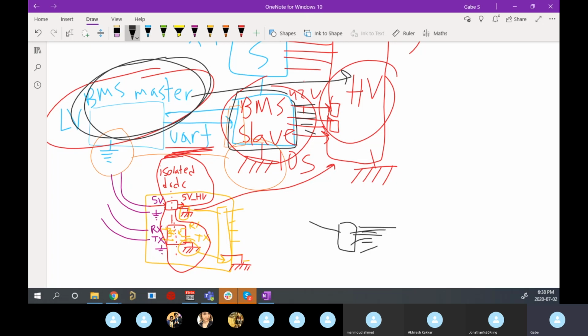So it takes all this parallel stuff and spits it out over serial communication protocol. And to the master, it turns out that's over UART. So to measure the whole battery pack, all of these temperatures, I guess not all of them, but all the ones measured by the slaves and all of these voltages, you only need 2 pins. Only 2 UART pins on your microcontroller and you can check out the whole battery pack. That's the beauty of a serial communication protocol.